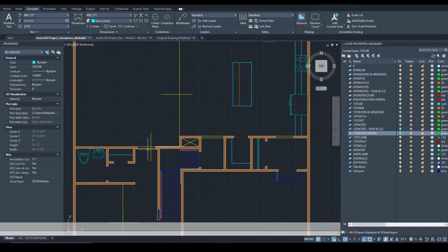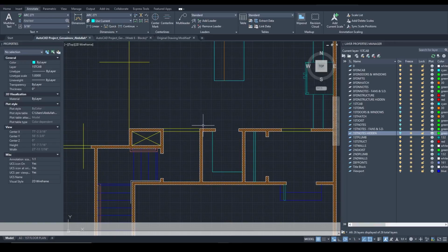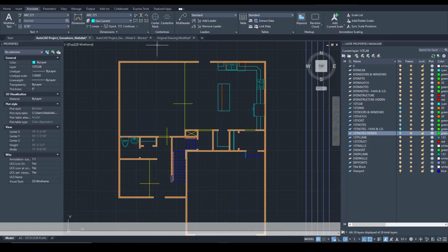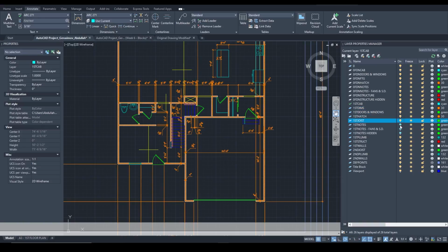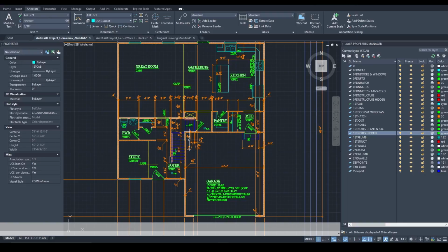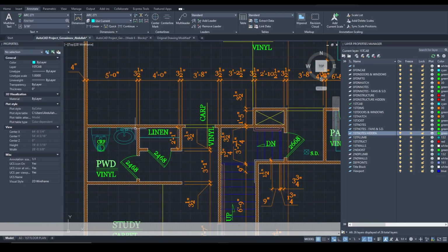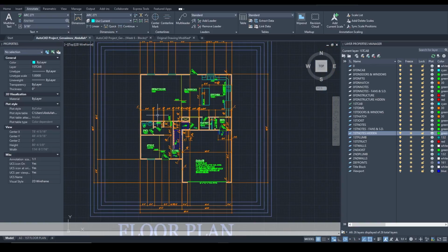Once you fixed all the corners and you got all the hatches in all of the wall cavities, try to omit the wall openings because we're not going to put a hatch between them, since this is something that we see above. Above hatches we're not showing in this case. So once you've done this and your drawing looks pretty much like mine, let's go back and put all of our layers back on. This way we're indicating our interior and exterior walls and they're absolutely clear. They're not going to be mistaken for any types of lines.